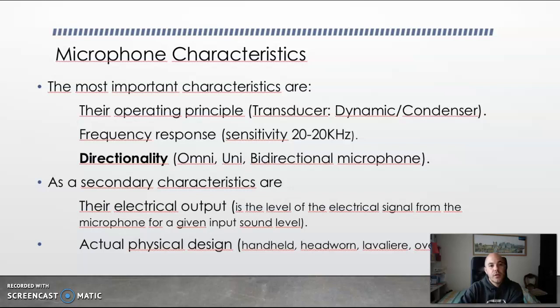First part, I'm talking about microphone characteristics. The most common characteristics of a mic are their operating principle, which is the transducer. It could be dynamic or condenser. The frequency response, which needs to cover the human ear response, which is 20 to 20 kilohertz, and directionality.